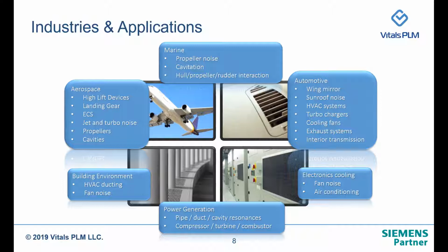In the building environment, again, there is a lot of HVAC ducting, and internal rushing flow could be a source of sound. The building environment also has a lot of fans, and noise is an important issue there. Finally, in the aerospace industry, the high-lift devices also have sources of sound, and the landing gear. During landing, when the landing gear opens up, the high-speed turbulent flow around the landing gear becomes the source for the sound.